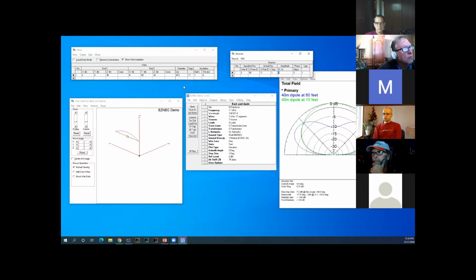Well, don't confuse the length of the antenna. So 68 feet is the length of our antenna. I was doing the Z's. Yeah. So if I ran them at 68 feet in elevation and looked at the far field plot, there was no straight up vertical bump. If you run it at 70 feet in elevation, you can see that hump in the very center. So that's vertical going straight up.